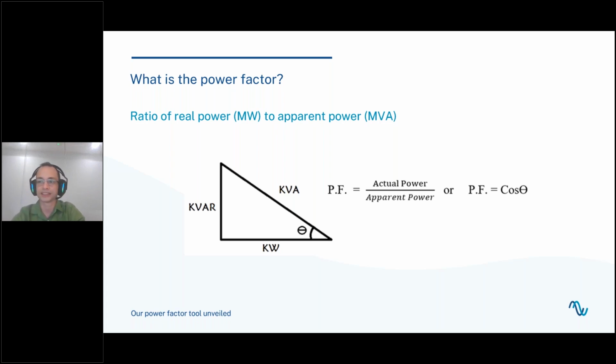This active power is the only power that is actually useful for our day-to-day tools. So our objective is to minimize the reactive power that we generate. Because of this, it's really important to keep the power factor calculations and estimations of our PV plants accurate, because we want to aim for a power factor equal to 1.